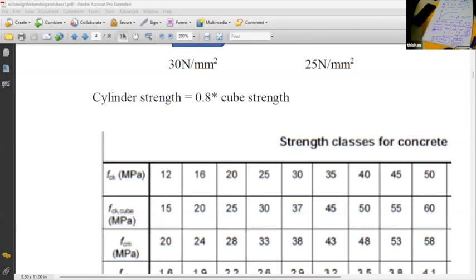Pre-stressed concrete members are thin sections, whereas reinforced concrete are massive sections. So in reinforced concrete construction, you can use fly ash, but even for pre-stressed concrete, you can use fly ash to reduce the cost of construction. Because it gives a very nice finish with a very good cover zone that is resistant to chlorides and sulfate. So in highway bridges, it's worth using 15% fly ash, even with pre-stressed concrete members, because you might be using various chemicals on the road.